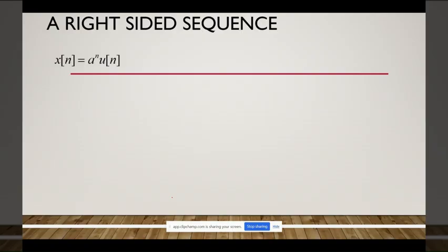Let us discuss the Z transform for an infinite sequence. We have to find the Z transform for the given signal x[n] = a^n u[n]. We need X(z) and its ROC. The general formula is the sum from minus infinity to plus infinity of x[n] z^-n. Since it is u[n], which has a value of 1 from n = 0 to infinity, the limits change from minus infinity to 0 to infinity, because u[n] has values only on the positive side.